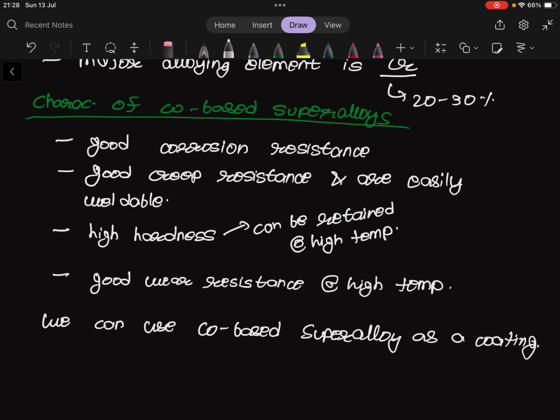This kind of alloy has high hardness and doesn't deform plastically, as we discussed. So we can think to apply this kind of alloy as a coating of turbine blades used in steam power plants, that is in low pressure and low temperature conditions, to protect the leading edge of the blade from erosion. So in the first case study of this lecture, we can go for studying the laser cladding process, which was used to coat the leading edge of the turbine to protect the martensitic stainless steel blade from erosion.